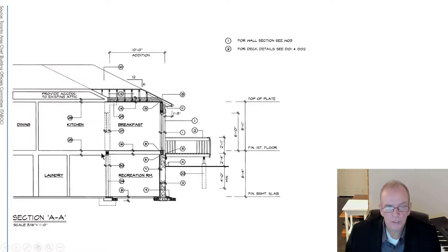Probably what I'd have to do is strap it down to make it line up with these particular joists, because they're probably the old joists. So whatever joist I use, they're not going to be exactly the same. If these are 2x10s and the 2x10s I'm using for a beam, these will be a little bit smaller than those. So a lot of these things you deal with in renovations that you don't deal with in new construction, but they're all little flags for me when I take a look at that.